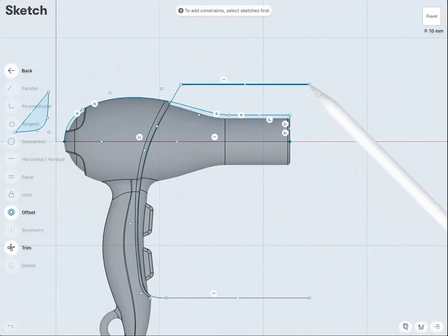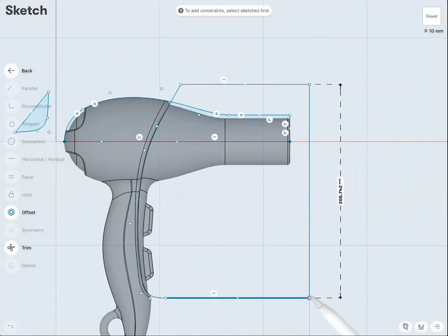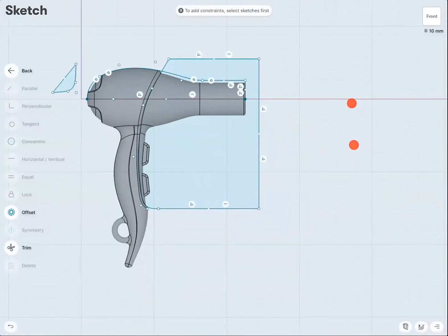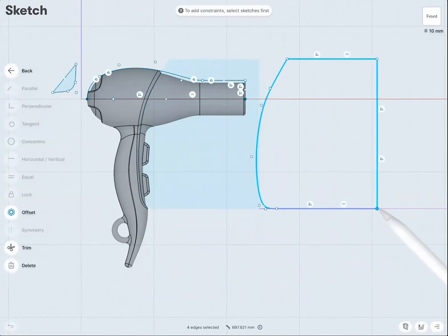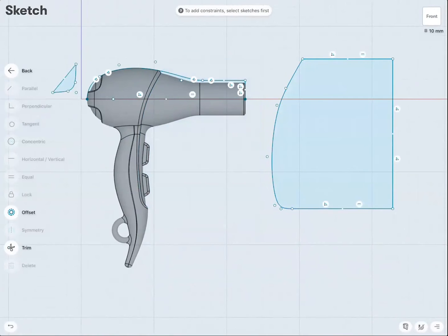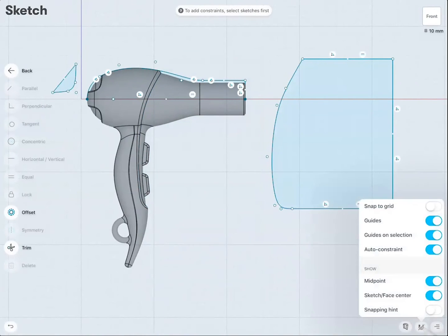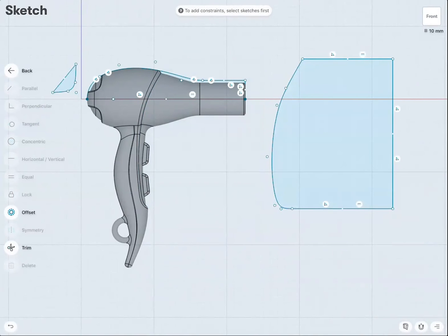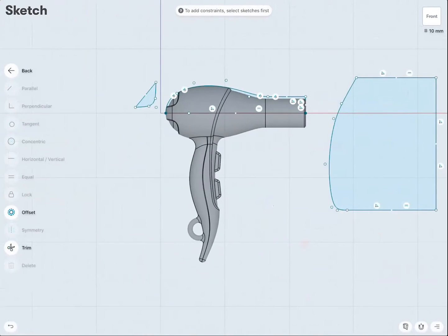And these 2 points are perfectly vertically aligned. Another nice feature of the interactive snapping. Double click, select this one point, and then along the guideline, I move this one away. And I will turn on snapping to grid again. Very nice. Okay, good.